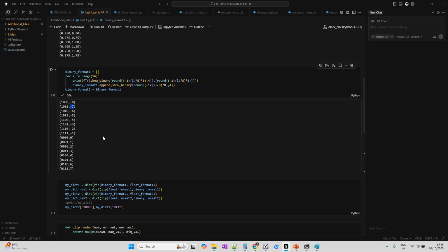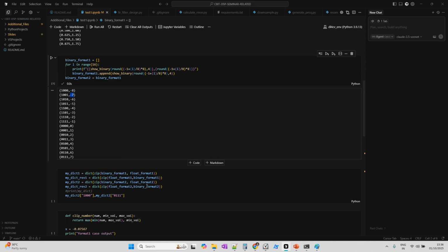At every stage of the multiplication, addition, all those things, you have to keep track of how the Q formats are changing. That's why fixed point implementation is very tedious. The very reason is that you have to keep track of how the Q formats are changing. If I put a Q format, is it going outside the Q format or not? If it is going outside, I might have to increase the range bits. All those things we have to take care of. So that's the thing. Next I will run this.